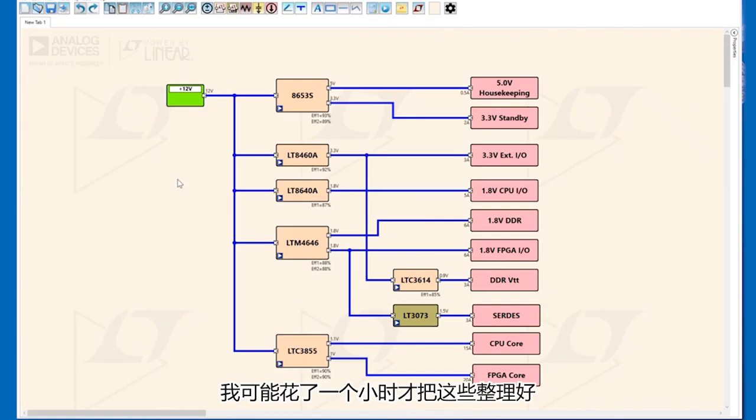And it probably took me an hour to put this together, just thinking about each regulator and choosing individual parts for it. Here's that LDO that we were just talking about, and I do have it running off the 1.8 rail, so that worked nicely. And here's that DDR termination regulator, and it's running off this 3.3 volt rail, so it's happy.